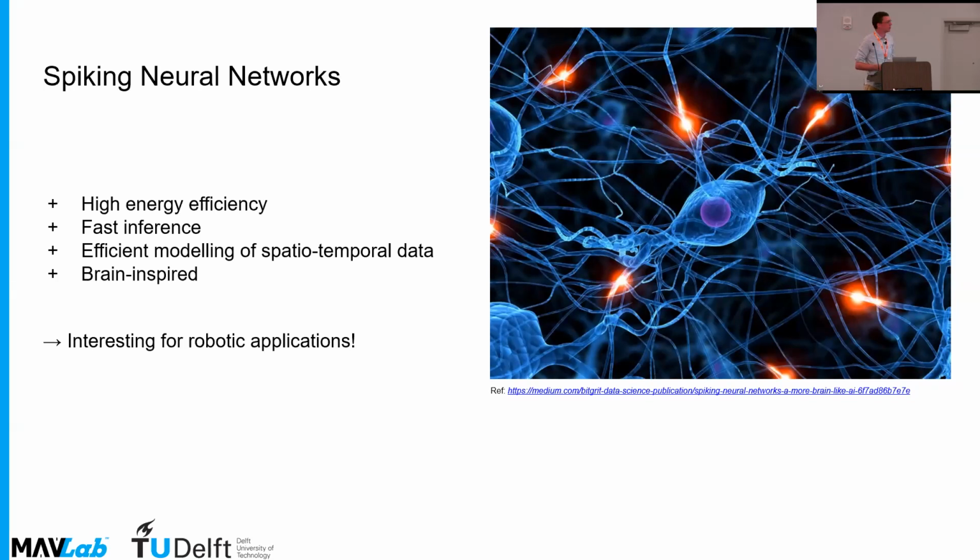But if we look at the work that I discussed before, where we calculated the thrust set point based on the ventral flow, there's also other parts that need to be addressed. So the thrust set point was calculated using this trained SNN, and this was sent to a conventional PID to perform the actual control. So still on a von Neumann CPU, and at some point, if we want to have this full neuromorphic pipeline, we will have to get rid of this as well.